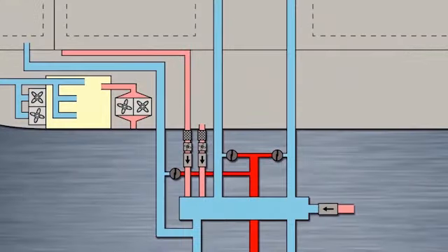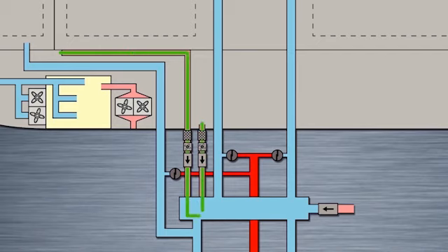The recirculation system supplies air for ventilation to the passenger cabins by collecting cabin air and mixing it with pack air in the main distribution manifold. The whole recirculation system's objective is to reduce the demand for fresh air from the pneumatic system, or engine bleed system, and from the air conditioning packs, making the process much more efficient. All the recirculated air is pulled through an air filter to remove very small particulates, bacteria, and microorganisms.